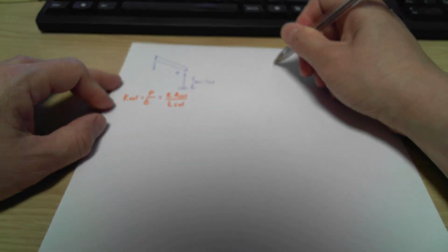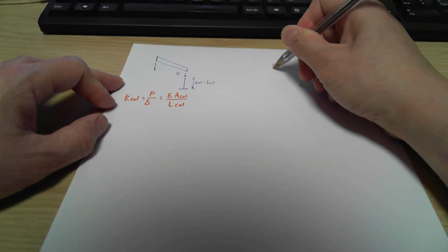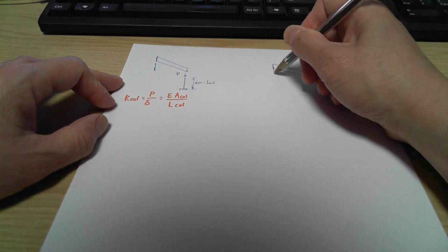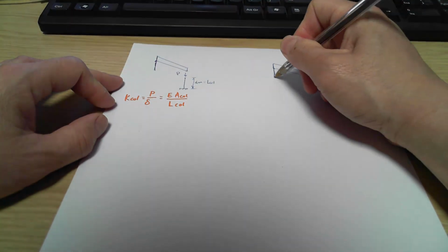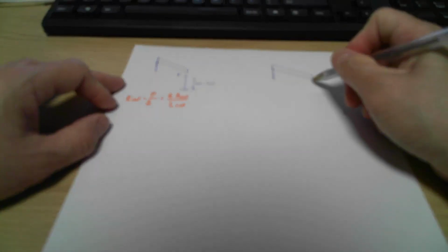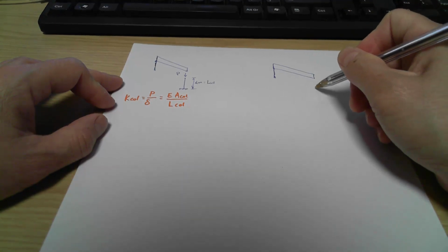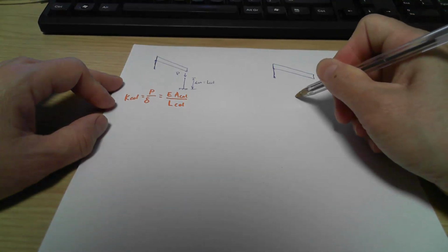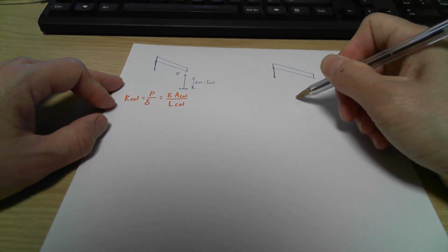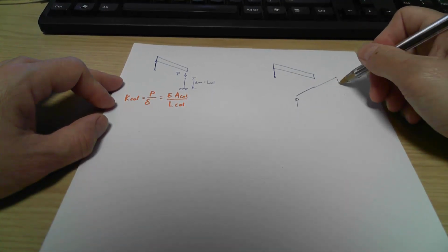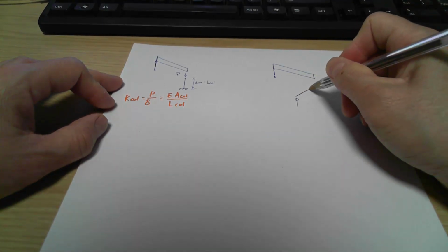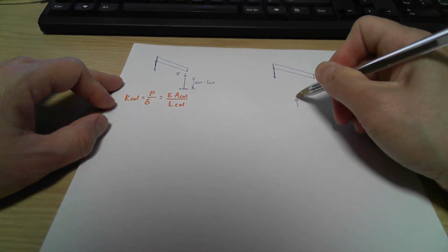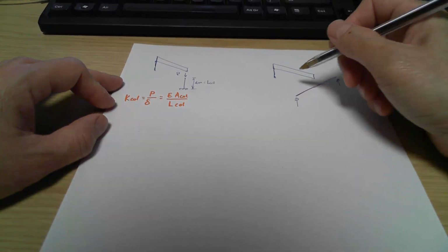And then the new structure we're going to create is like this. You have a truss in here, and the left hand side is connected, no change at all. But on the right hand side, the column is going to be removed. So I isolate this column and the beam and show it here. That's the size of the beam, and it is going to be assumed simply supported by some other structures, on a wall or on some of the other columns, 6 meters apart.